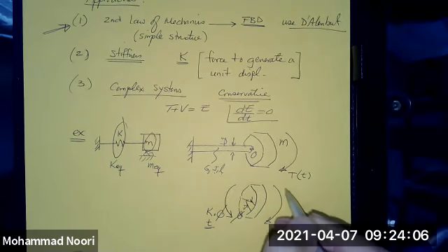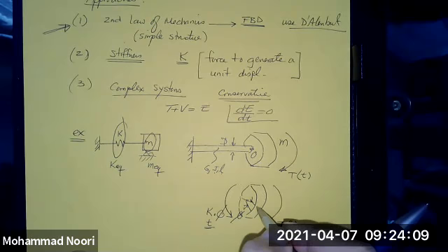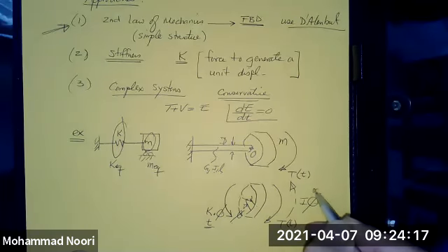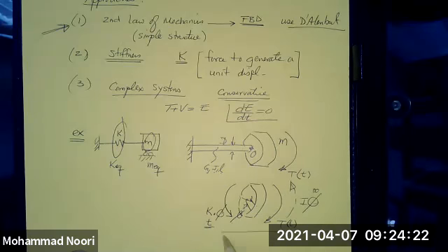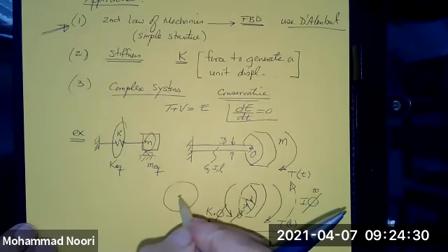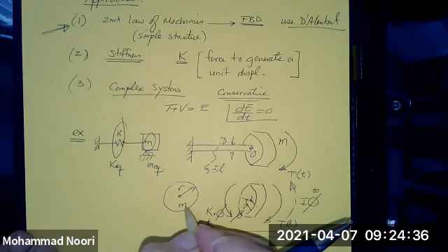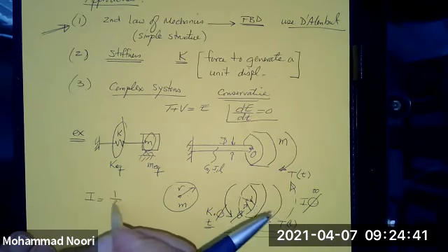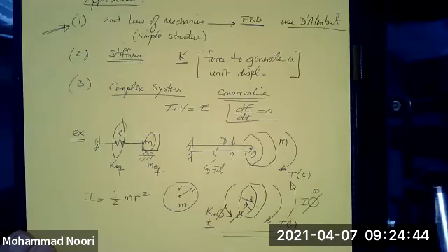And then, of course, we have the motion. This is a mass. So we need to also use the inertia force here that is in the opposite direction of the motion, and this is the free body diagram that we were looking for. Okay, remember, if you have a disk with the radius r and mass m, I is simply 1/2 mr squared.